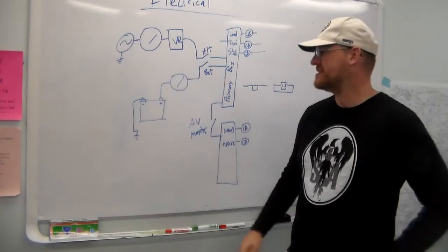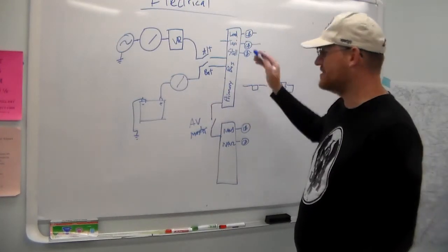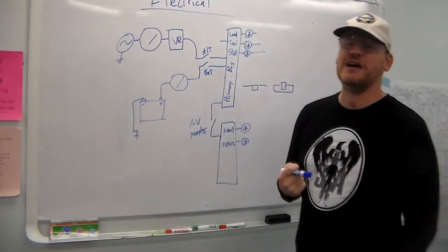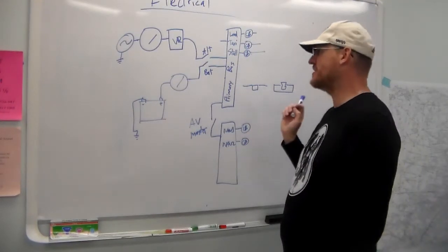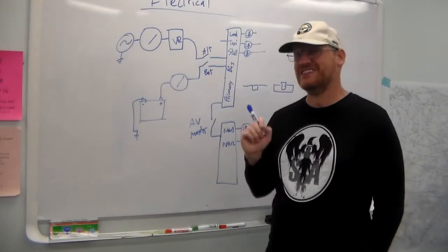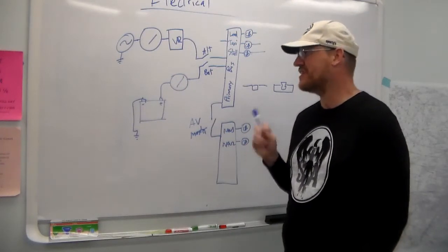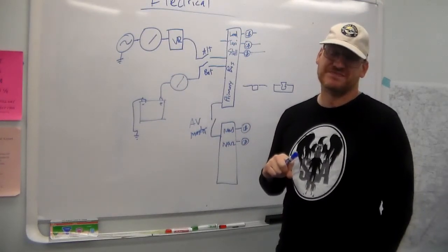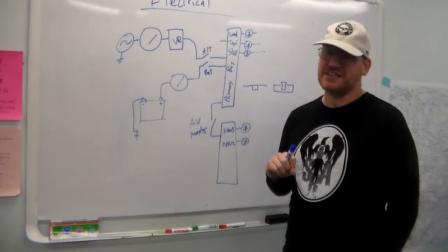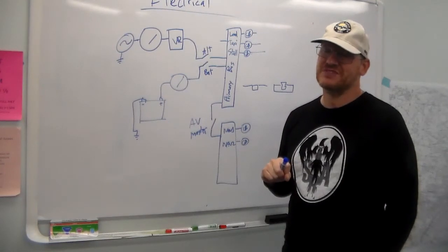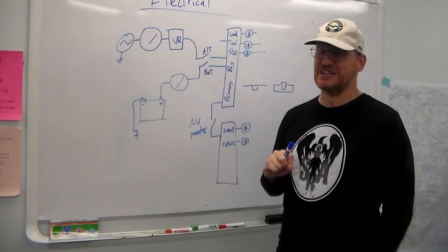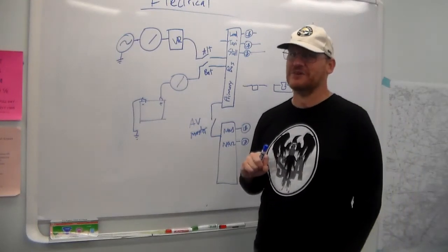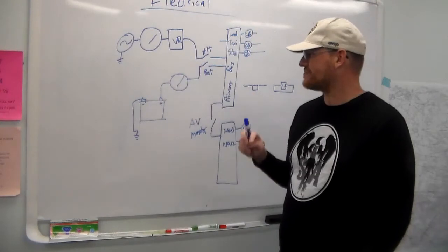You know, speaking of resetting things, we talk about the circuit breakers. What do you do if it pops? Well, if it pops, if it's an essential system, you can try to reset it. If it pops again, leave it alone. Don't keep trying. In-flight fires are not fun, especially electrical fires that might be in the cockpit.